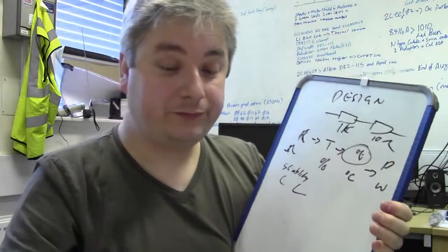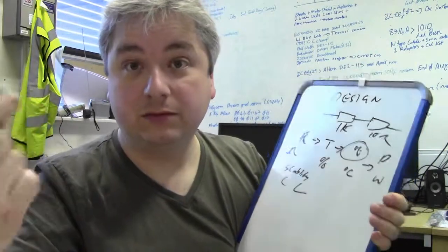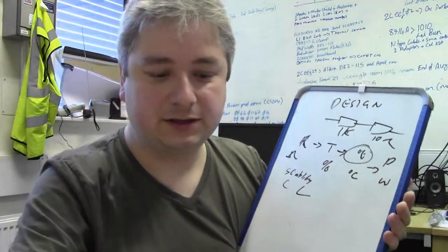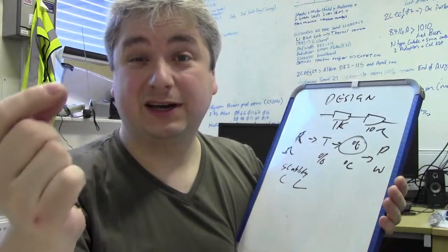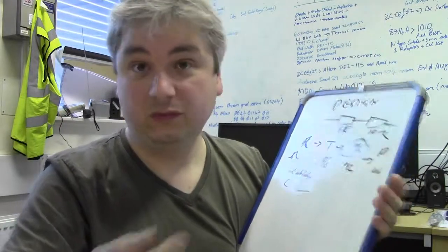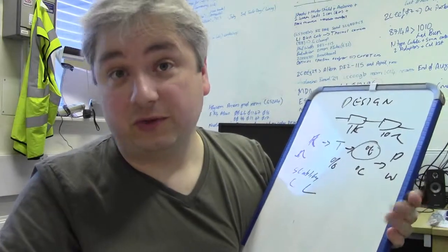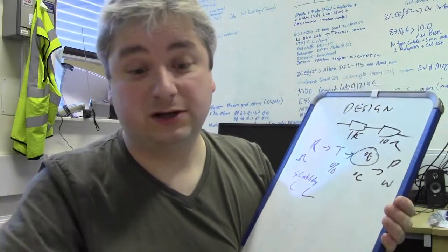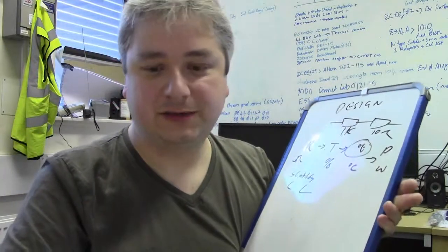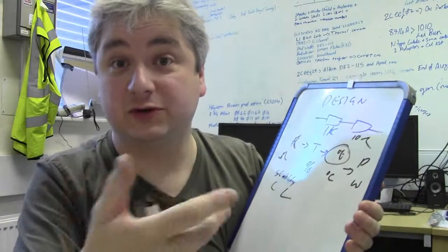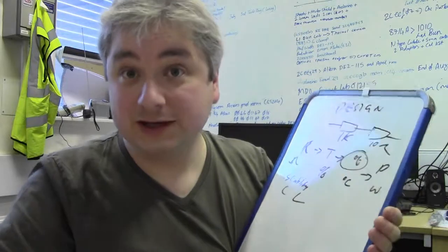inductance in there. So you have to imagine, wire wound, it's a coil. Coils have inductance. You will get some inductance. Same with these, you've got a lead on here, you've got wire. The wire on its own will have a stray inductance. For general purpose circuitry, it may not be a problem. For RF design, or radio design and things like that, it all adds up. Can be a problem. Things like capacitance, if it's wire wound, you're going to have some stray capacitance between the windings. So it's going to shift your RF signal, so it's quite important.